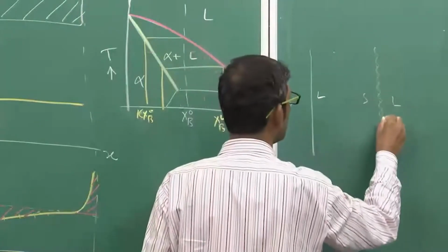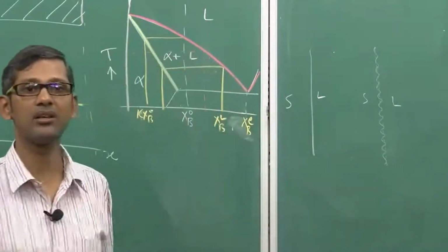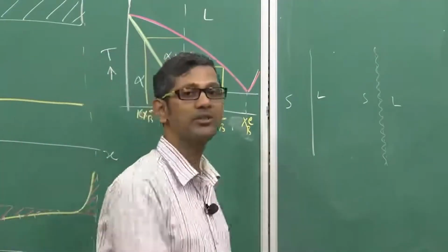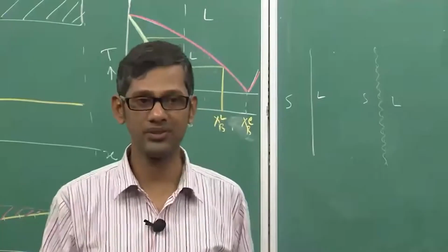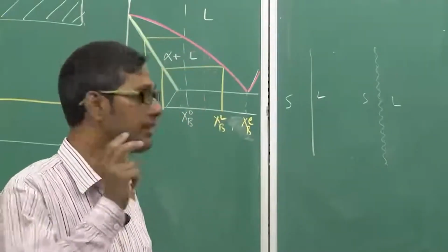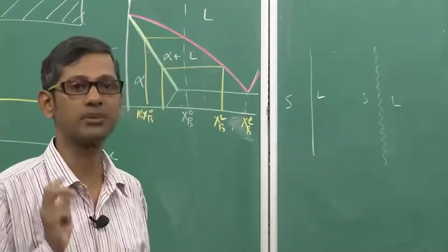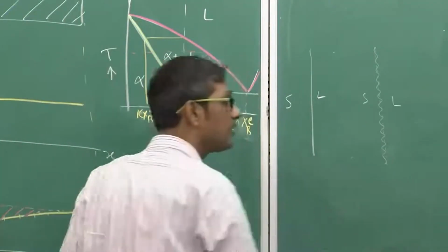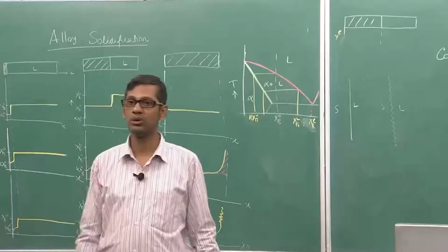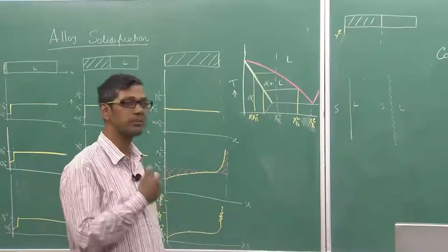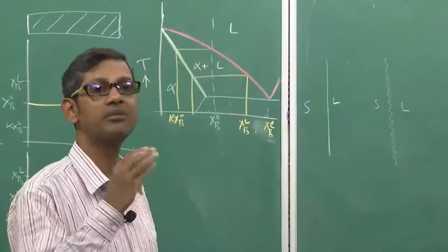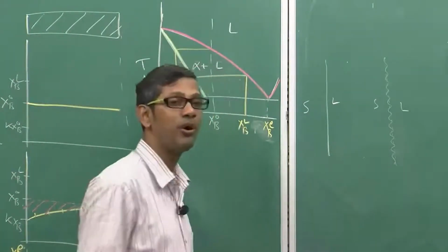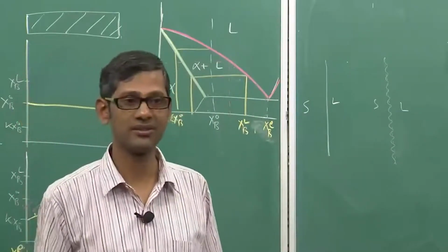You see, this is a sinusoidal curve. You can also have cosinusoidal or any other kind of perturbations. Now the question is this: because of compositional change or temperature variation across the interface, a certain kind of perturbation has developed, understandable. Now the question is, under what condition will these perturbations grow? They have two choices: either the perturbation will vanish and the interface will remain flat, or these perturbations can grow and form again cells and dendrites.